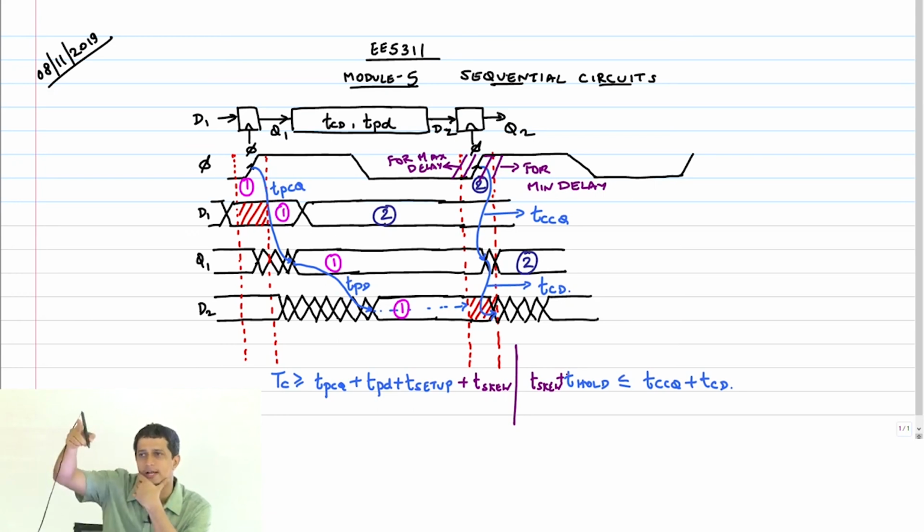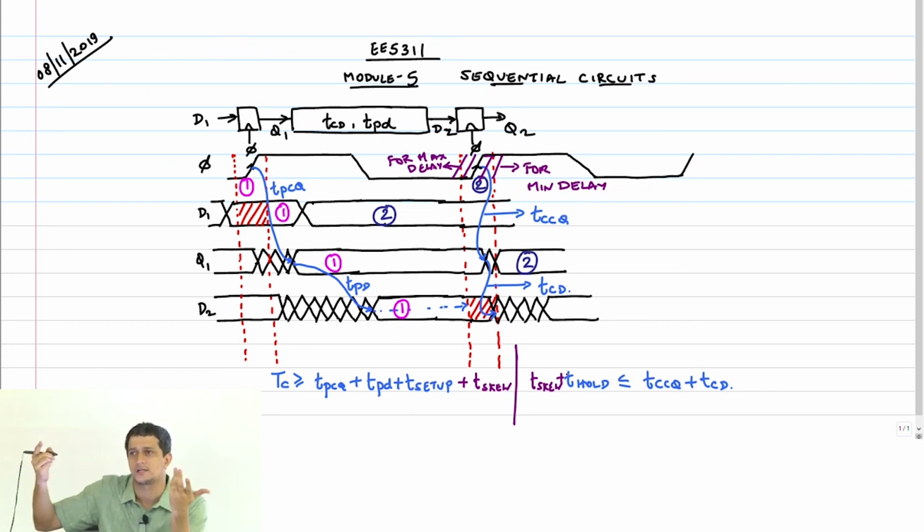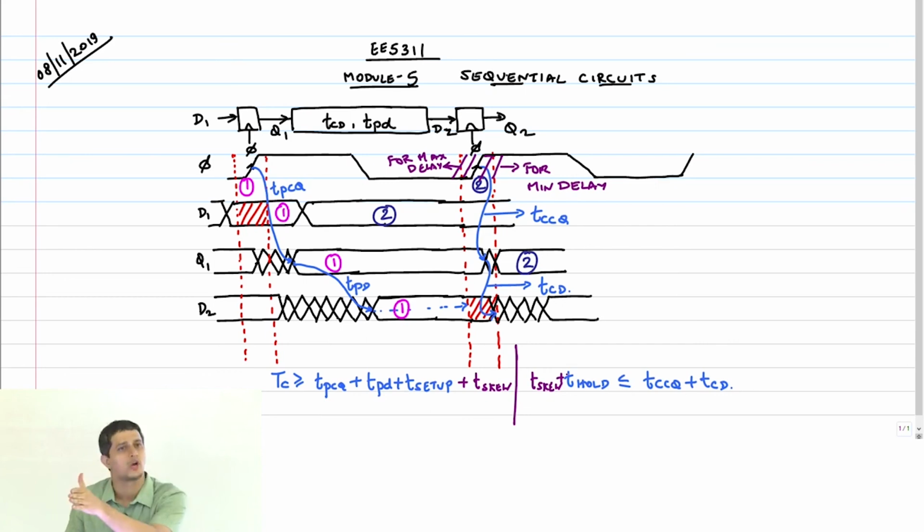You had a question yesterday as to what is it that is getting contaminated, right? So hopefully this picture should make it very clear. Practice drawing these waveforms one after the other, max delay, and then you look at the min delay, right? Otherwise you do not know what state the earlier thing was in, and therefore you are not sure it's actually getting contaminated. That's the problem.